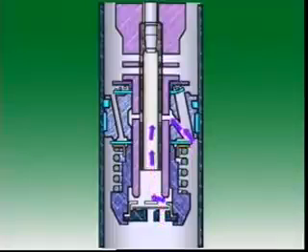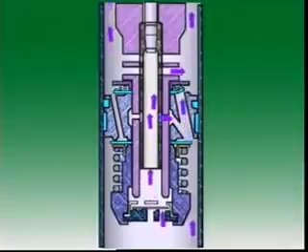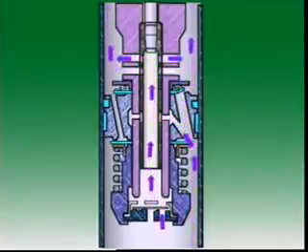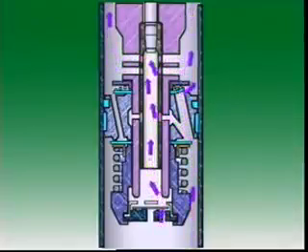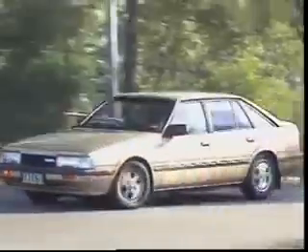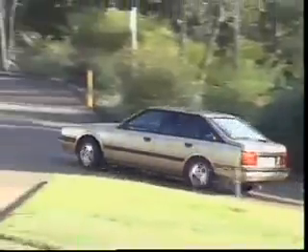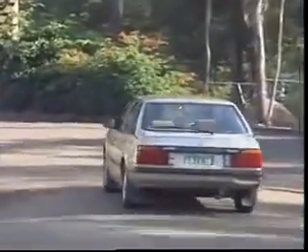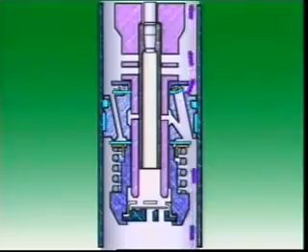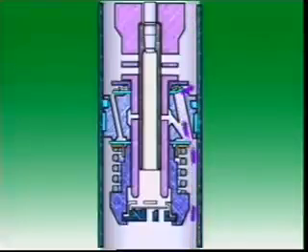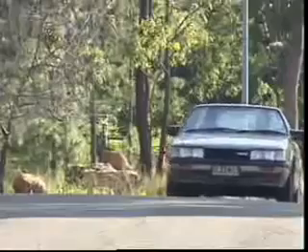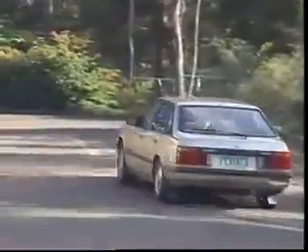In this position, all orifices are open. Oil can flow more easily through the passageways in the piston. Only a small dampening effect is applied to the oil. This provides a dampening force that emphasizes ride comfort when traveling at low speeds. Closing some orifices makes it harder for fluid to flow through the piston. This increases the dampening effect of the shock absorber, providing a firmer ride, more suitable for higher speeds and faster cornering.